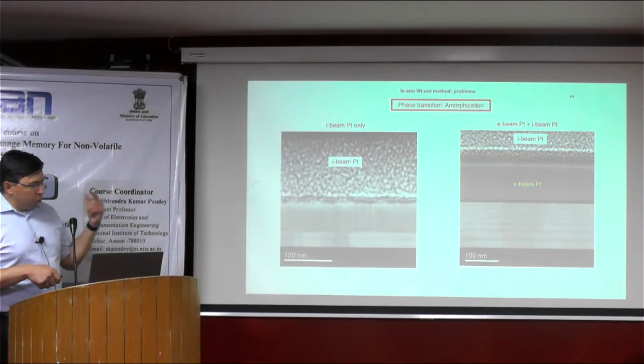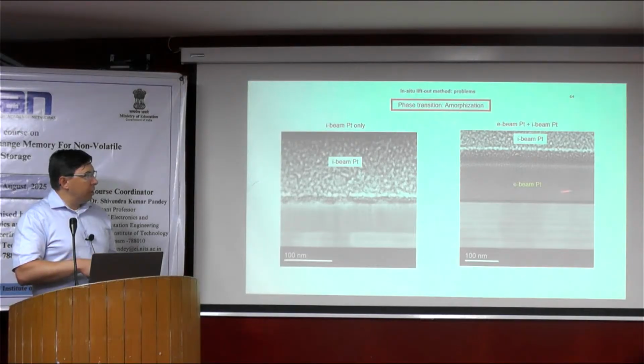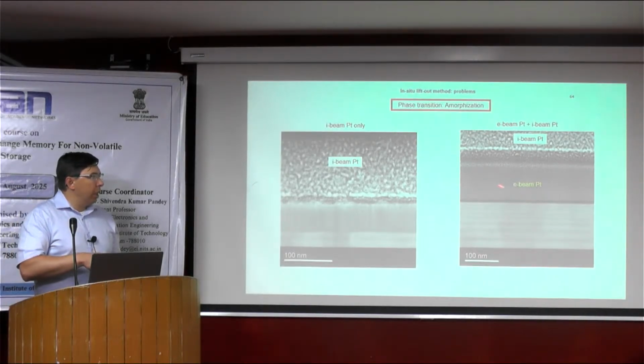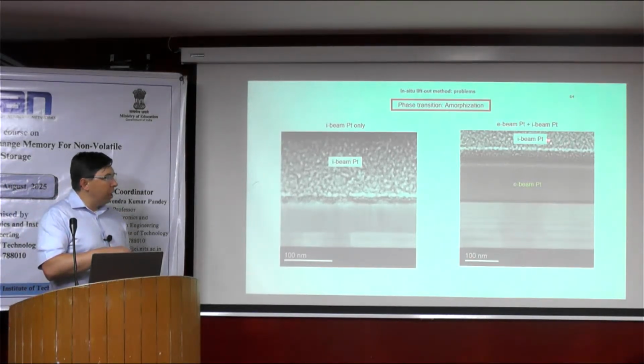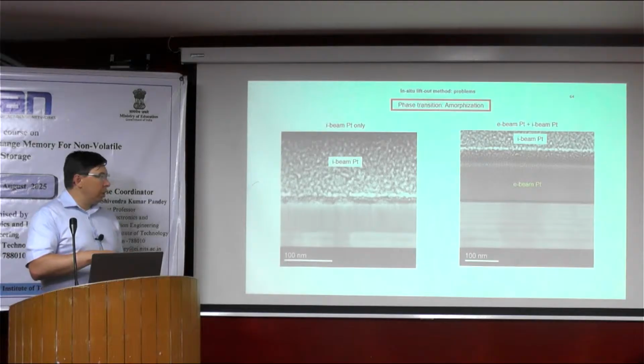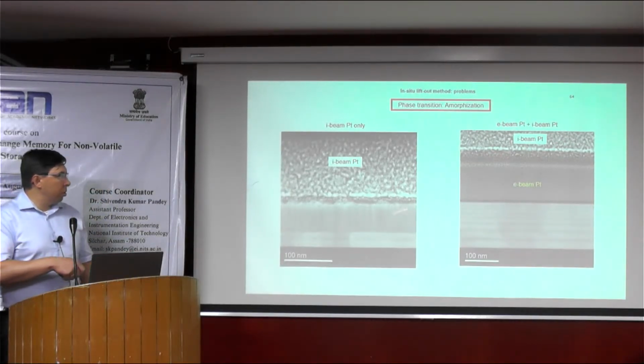So you should be aware of this, and please always use extra layers, like deposited directly in the system or externally. Here you see that the thickness of the electron beam layer is more than 200 nanometers, and even in these layers, the ion beam platinum can go to some extent into the E-beam layer. So just think about this: the high energetic ion beam can destroy your structure.